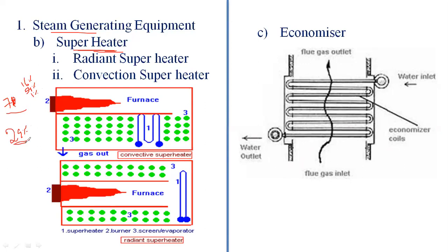We are reheating in the intermediate stages using the flue gases, through the superheater, air preheater, and then economizer. The efficiency can be improved by 5 to 10%. That is, the efficiency we can bring from 30 to 35%.